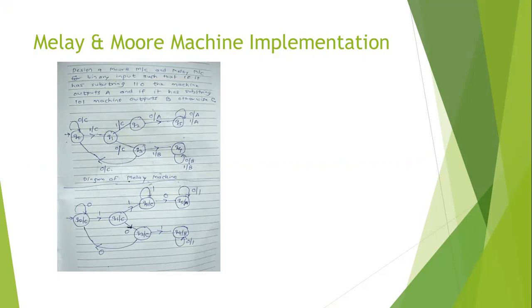And after that, whatever value I'm getting, 0 or 1, the output will always be A, because I already got the substring 110. So why is the self loop 0/C given? See, if anything is coming before the 110 substring, that is also possible.